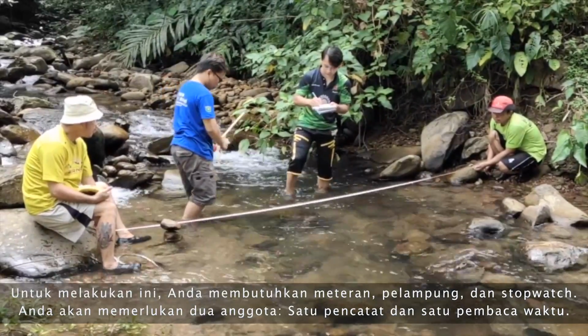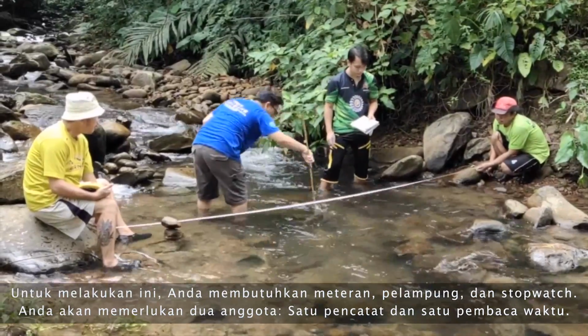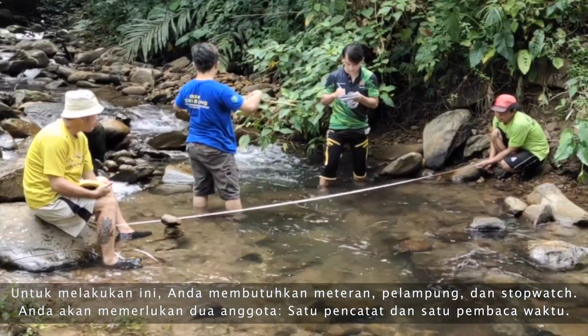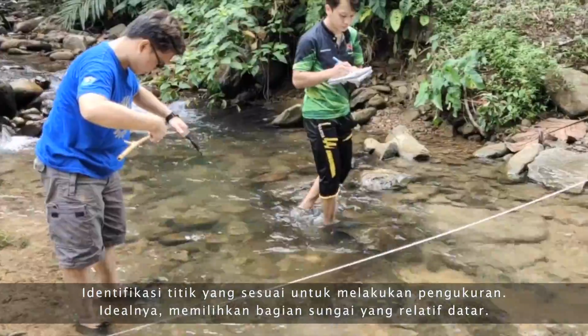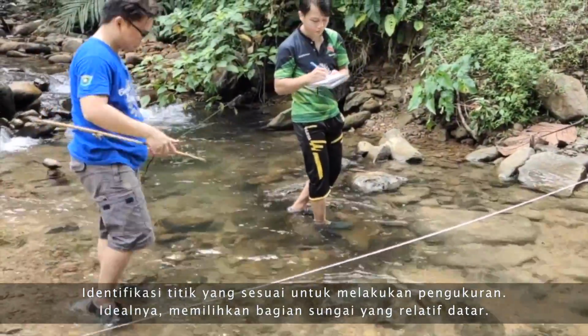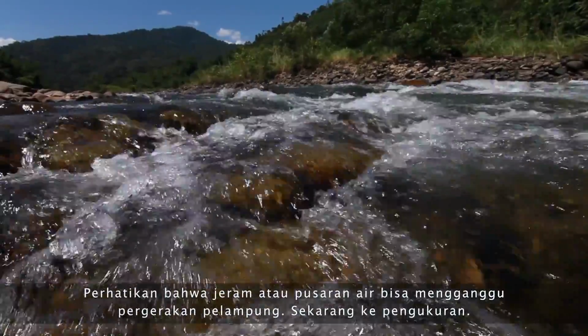To take these measurements, you will need a measuring tape, a float, and a stopwatch. You will need to assign a note taker and a timekeeper. Identify a suitable site to conduct the measurement. Ideally, this will be a portion of the river that is relatively flat. You do not want to have rapids or eddies interfering with the movement of the float.